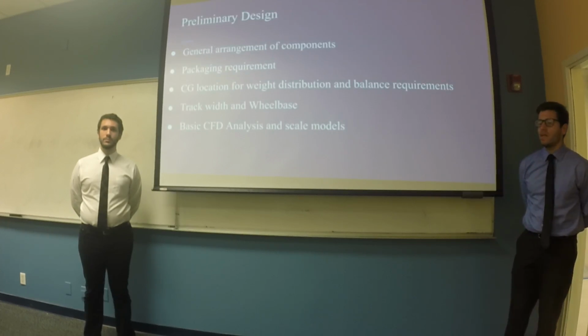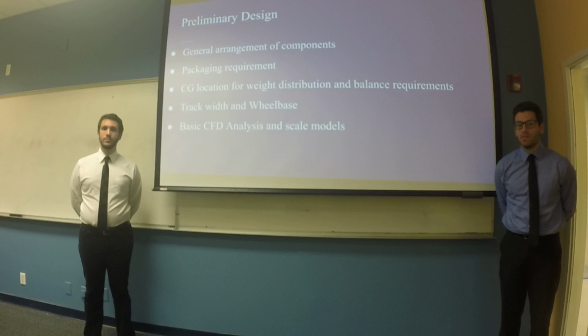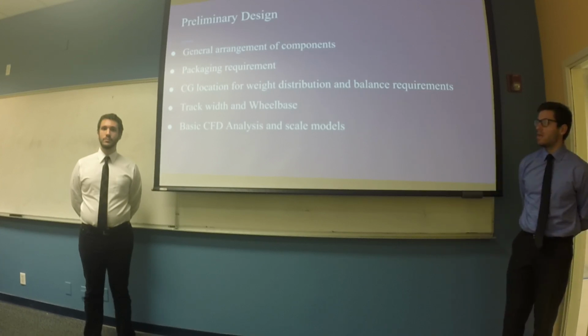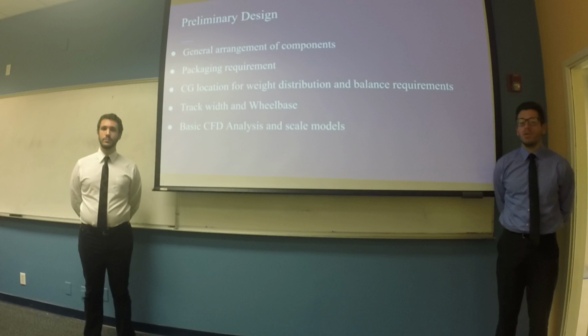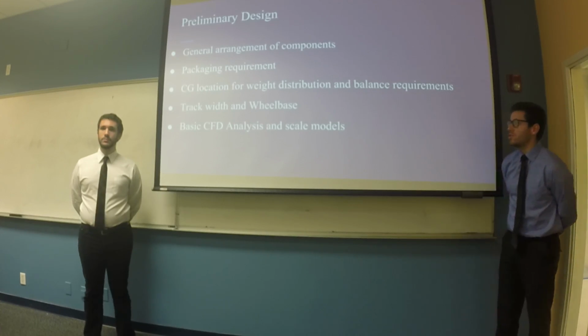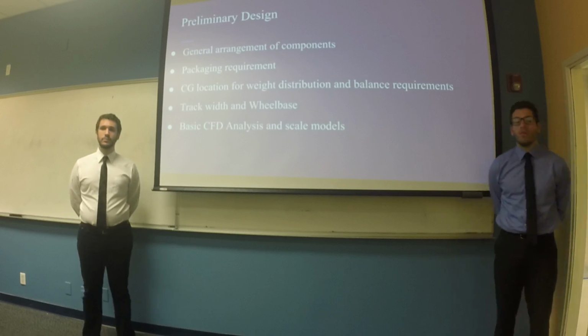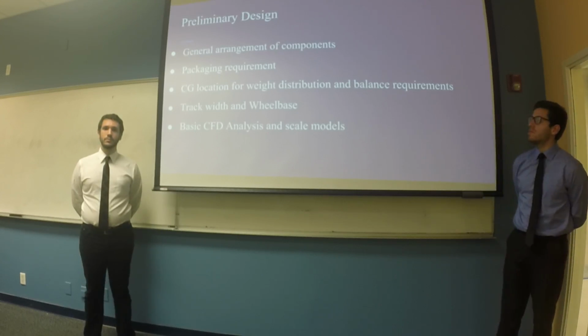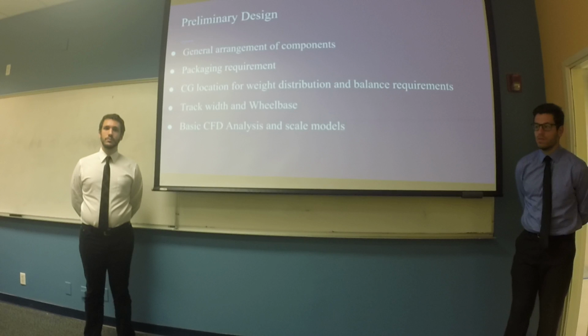Your preliminary design is basically like your napkin sketches. This is going to be an idea sketch of your general arrangement of components, the packaging of these components, your center of gravity location, your main track width and wheelbase, as well as basic CFD analysis and scale models.